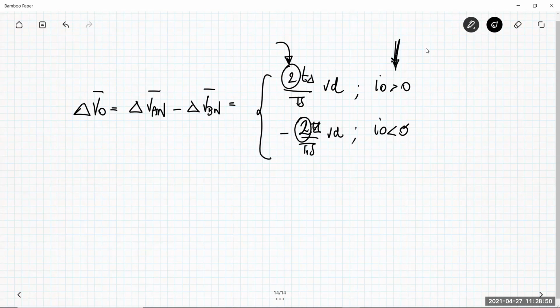In all the situations in which your filter characteristics are not so good, because your L or your R of the motors are not known, or maybe they do not give a pole that makes it possible to reduce the harmonic content, having a spectrum in which the first high order harmonic is twice the switching frequency can help.